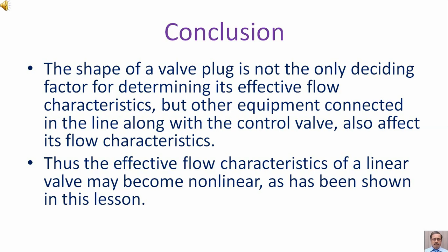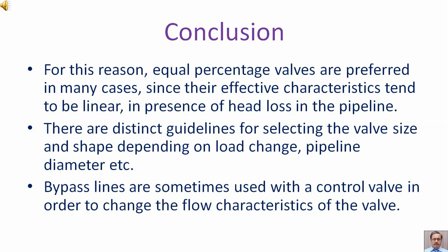Thus, the effective flow characteristics of a linear valve may become non-linear, as has been shown in this lesson. For this reason, equal percentage valves are preferred in many cases, since their effective characteristics tend to be linear in presence of head loss in the pipeline.